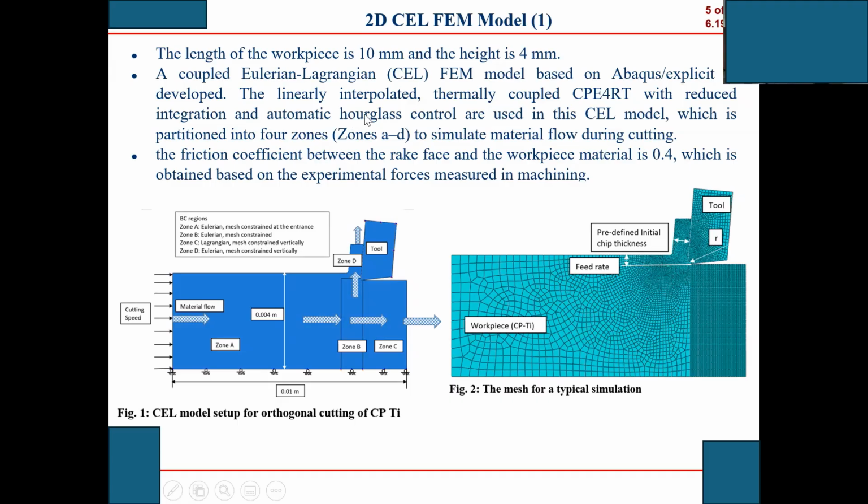So the linearly interpolated, thermally coupled element. Usually FEM is used to solve for the displacements, but for this we use these elements, and they couple the displacement and the thermal. This is CPE4RT, with reduced integration and automatic hourglass control used in this CEL.